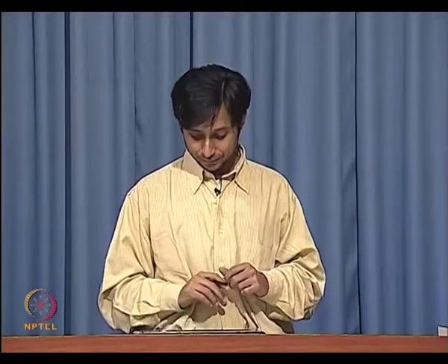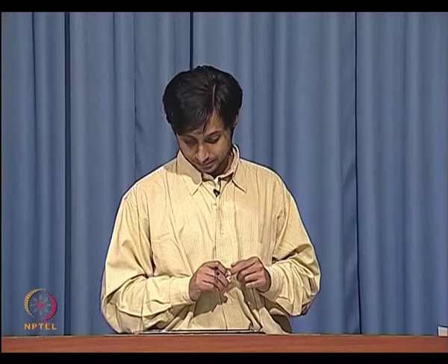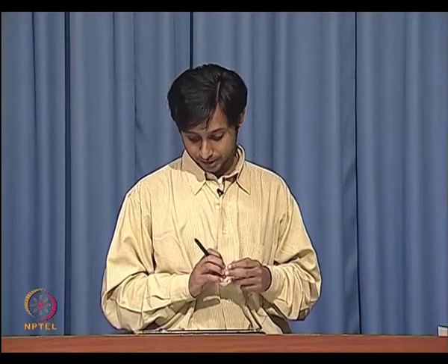You have got to block out DC. The way to block out DC is by using a high pass filter like this, and a high pass filter like this looks easy on paper, but when it comes to making the components, it is impossible to fit the components inside an integrated circuit. So, even when you make 8 nanofarads, even then you have got to realize that you have to make about a mega ohm worth resistance, right. So, that is a large resistor that you still have to make, even that is going to cost you a large amount of area.